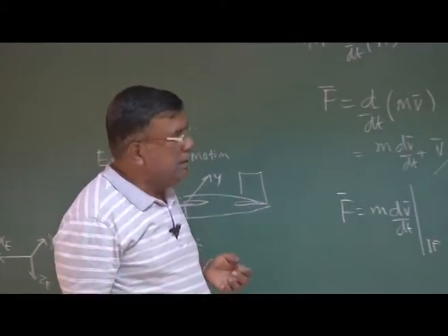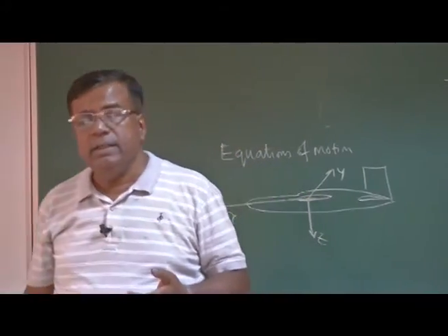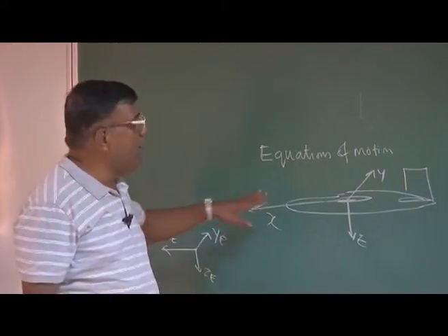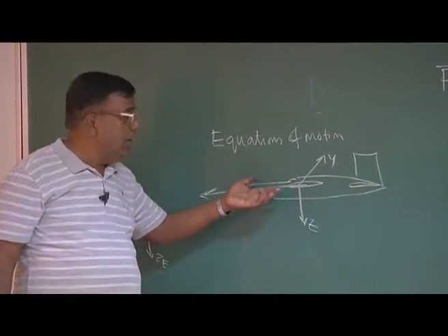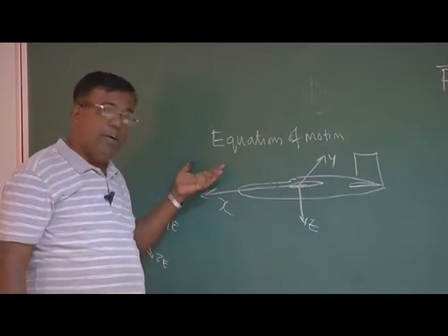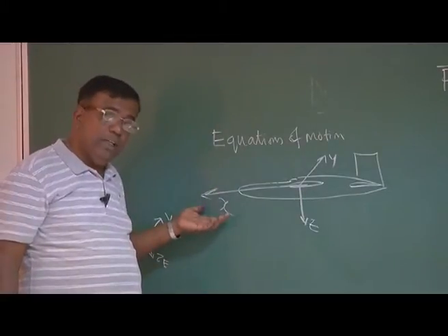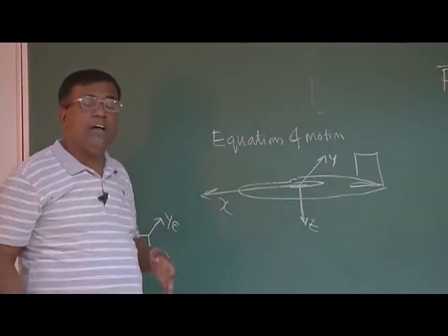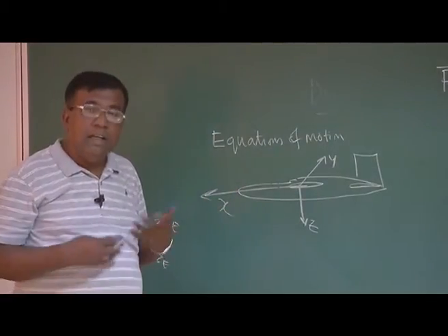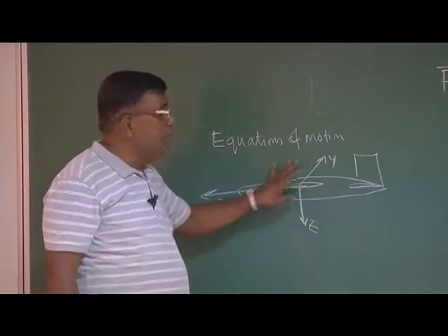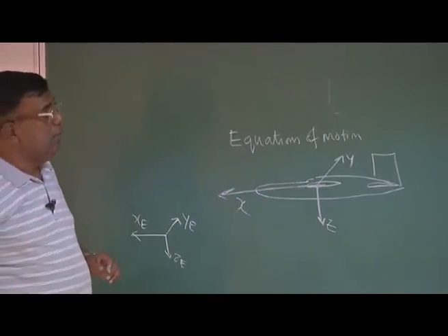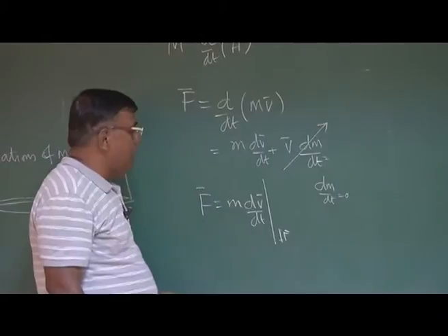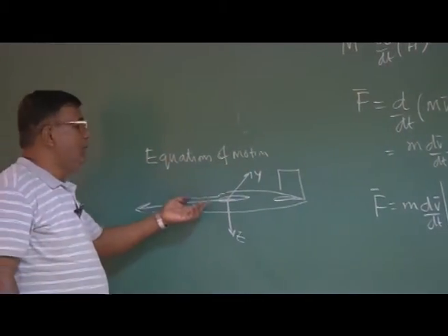The second thing we realize is that the aerodynamic forces depend upon the relative airspeed. So from that angle, the body fixed frame will be very, very important. The speed of the aircraft with respect to the atmosphere, relative to wind, will be very useful, because aerodynamic forces depend upon relative air velocity. So we had a motivation to work in the body frame for these two reasons. But how to do that? We need to work in an inertial frame, but we have a motivation to work in the body fixed frame.